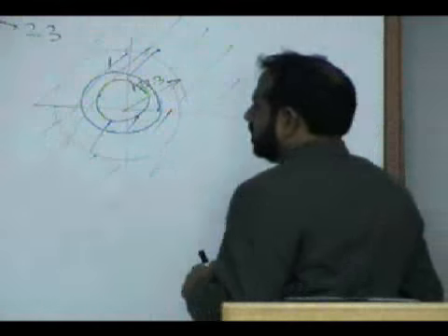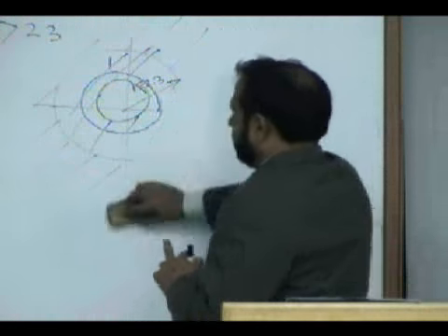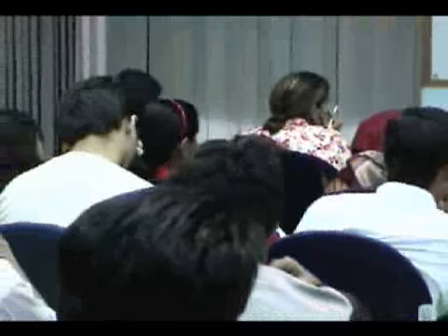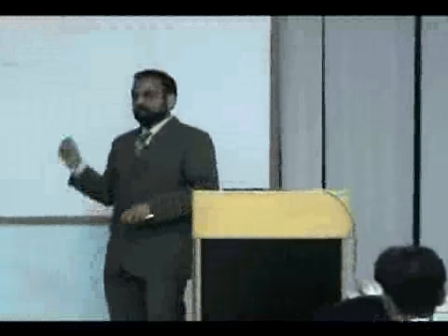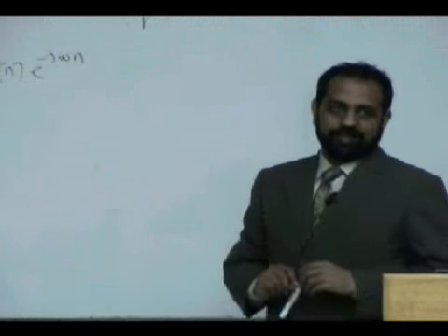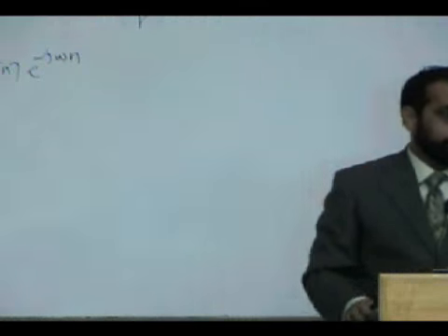So this is the motivation of computing the Z transform: to comment on the stability of a system. Our interest is not in finite impulse response systems, our interest is in infinite impulse response systems, because their stability is a question. So you don't compute the Z transform for a finite system.